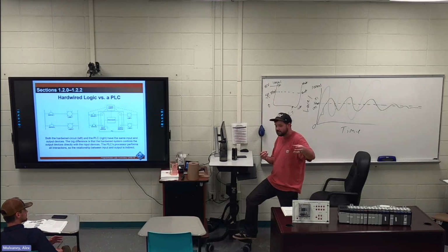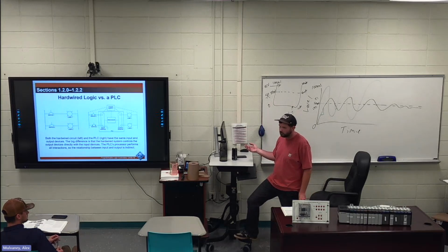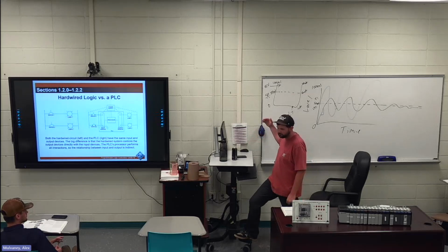So do I have a signal? Does my solenoid feel hot? Is it getting power? That's the first thing I would have done. Mm-hmm. And if it's not, you got to go see why it's not. Why is him forcing it on or off, however he's doing it, being written to that output and the output not firing? Because something's being written on top of it.